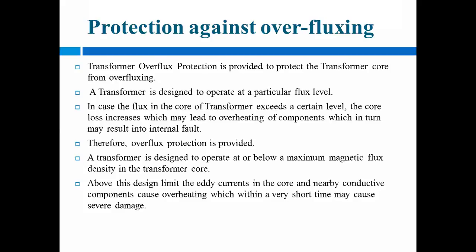So when we consider the EMF equation, E1 is equal to 4.44 f phi m N1, and E2 is equal to 4.44 f phi m N2. If we consider the normal condition, suppose only the primary side, then the supply voltage, or the induced EMF, is equal to the supply voltage for an ideal transformer.